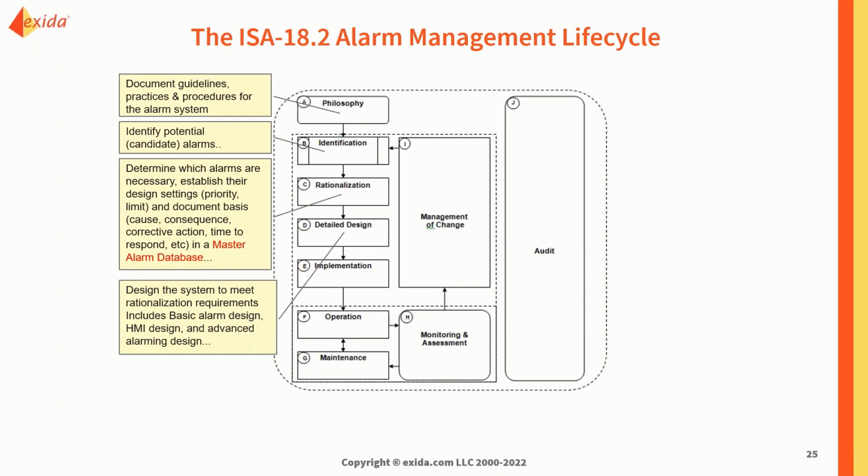Usually, a compressor has some other equipment associated. There might be some filter, and maybe they would set up some kind of alarms as well. Even pressure, temperature, those are also going to come into play. So what we're trying to do during the detailed design is basically identify the first alarm that's going to come in, and then we try to silence the rest of the alarms, so that the operator is not going to be overwhelmed when they see a sea of alarms coming in at the same time.